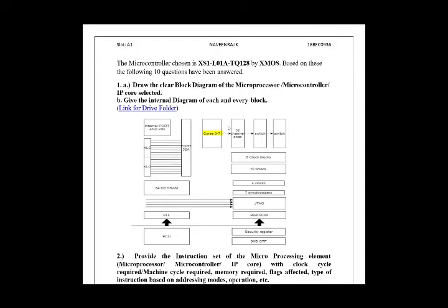As said earlier, the microcontroller consists of a single X core tile, which means there are 7 logical cores from 0 to 7, and there are 32 channel ends, 6 clock blocks, 10 timers, 4 clocks, 7 synchronizers, JTAG, boot ROM, security register, and OTP port. Let's discuss one by one briefly.